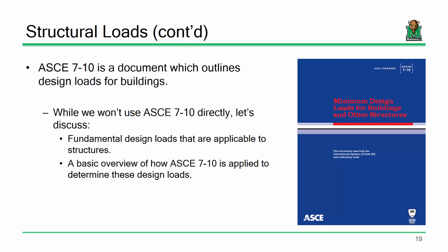To get specific on snow, the way that we address snow loads in structural engineering is, first off, there's a host of weather stations around the country that collect snow data for the entirety of the country. And with every edition comes the release of a snow map that reports ground snow loads for given regions. To give you an idea, the country has a snow load map, and then there's one particular state that has its own snow load map. Which state is that? Alaska. Alaska has its own snow load map because it's Alaska, right? So every now and then those snow load maps get updated. I guarantee you there's going to be minute changes from this spec to the next one. That's a good question. Everybody else good on that? This is good stuff. I want to make sure that everybody's clear on this.